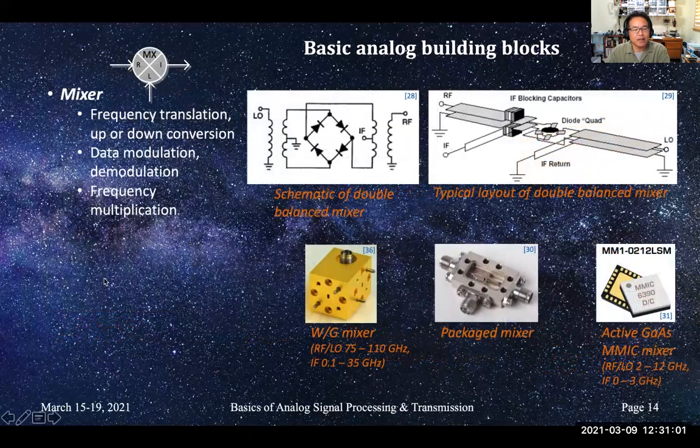Mixers, this is a key component, used for frequency translation, down conversion or up conversion. Here is the schematic equivalent for a double balanced mixer, and topological layout. Here's a waveguide mixer, connectorized mixer, and a gallium arsenide MMIC mixer.